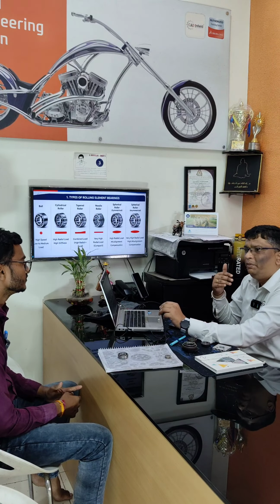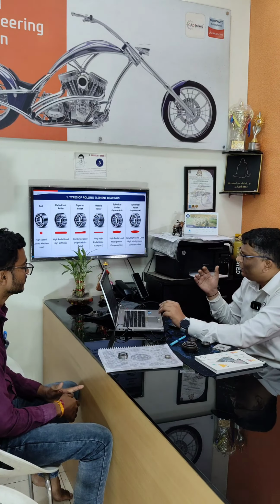If the speed is higher, the torque required is lower. So for high speed applications, we go with ball bearings. For high torque applications, we need a tapered or spherical roller bearing. Here you go through the different contact points. Ball bearings are for high speed, and spherical roller bearings give you high torque but at a lesser speed.